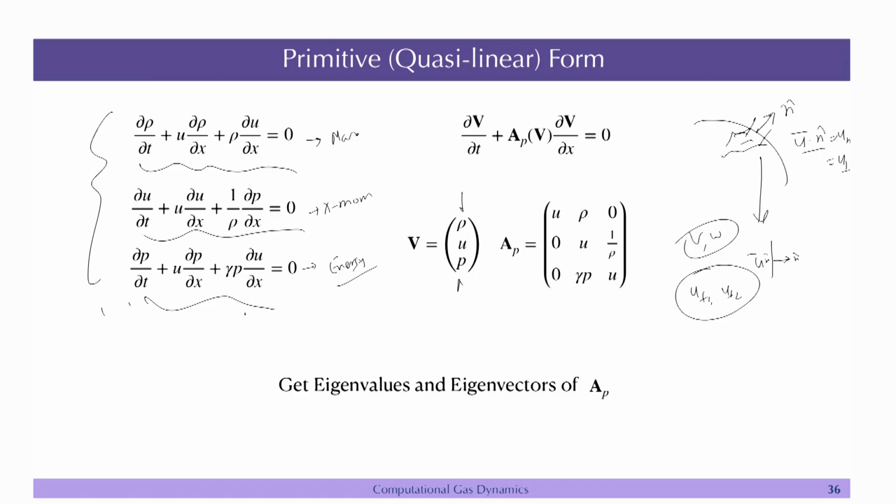Another question you may ask is why we are discussing the Euler equation, because most of the flows are viscous. The argument is that you can get the characteristics for the Navier-Stokes also, but they are fairly complicated because of the second gradient term coming from the viscosity, and much more complicated in compressible flow. But let us say you try to do a simulation around an aerofoil, you will have the far field boundary, or the inlet and outlet, sufficiently far away from the body so that the viscous effects are negligible. You can neglect the viscous effects here.